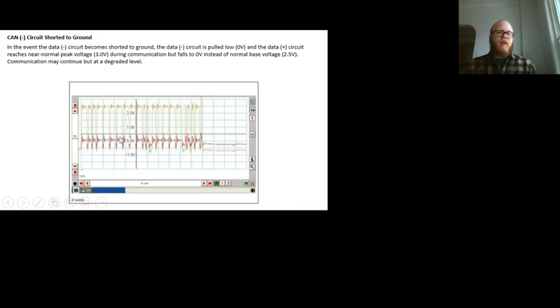But the way that these modules really pay attention to the information is, in this case, we're waiting for voltage to rise up past a point, I believe, because it looks like our low side stays down around 0 the whole time. But we look for voltage to rise up past a point, and then it uses its little clock to count. Okay, so it rose up past, let's call it 2 3/4 of a volt.